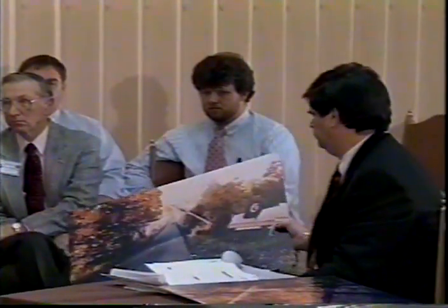The shoulders had been brought up such that they were flush with the pavement surface, and the pavement striping had been placed on the pavement. And as far as the yaw marks that are referenced in another report and may be referenced in your report, does a photograph give you the ability to measure a yaw mark such as the photographs you've seen? A photograph could if it were photogrammetrically correct and taken with appropriate measurements and reference points. In this particular case, no, it would not be possible just based on the photographs because of the perspective of the lens. It would not be possible to measure lengths or angles correctly.